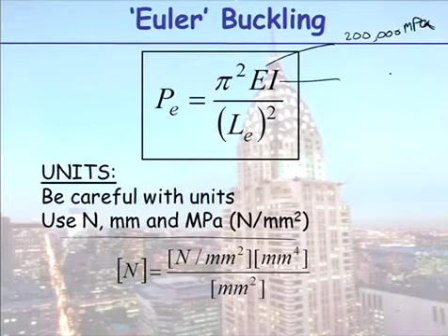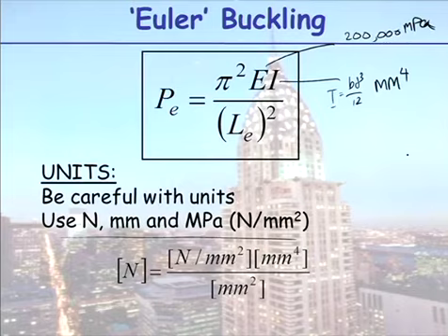And this I value, well, this is a BD cubed on 12 term, and these dimensions are usually of the order of millimetres. 100 by 200, 50 by whatever. So what are the units of I? Millimetres to the power of 4. So usually length in your diagrams is given to you in metres. Just remember to convert that to millimetres.